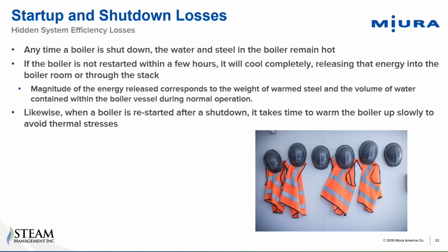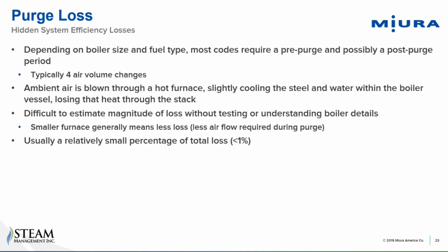Similarly, when a boiler's restarted after a shutdown, it's going to take time to warm up the boiler, to warm up that system. Depending on what you're doing with that heat, you may be dumping steam, or you may be blowing down a lot, or returning condensate that then sits in a tank. So you may lose heat that way as well. Startup losses are a little more difficult to calculate, but they're a significant loss as well.